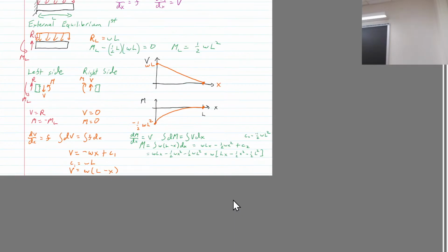And it's causing this to happen, right? But where is this located? It's located on the neutral axis. We just wrote M y over I, right? And if y is equal to 0, then there's no contribution to that stress. So what do you mean A is on the neutral axis?